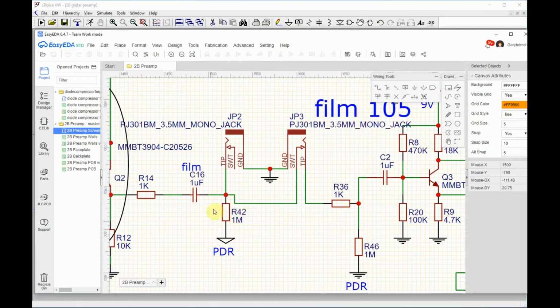First of all, you've got to think of pull down resistors, keep things at ground. And you need to think, well, what input impedance am I going into when I leave the effects send, and when I come back, what am I going to see in terms of the effects return input impedance? So these are things to think about. The first thing I'll say is the effects send is usually lower impedance, but not always, because sometimes people just don't put the circuitry in to bring it down. I think in my experience it's usually kind of low, maybe 1K or less.